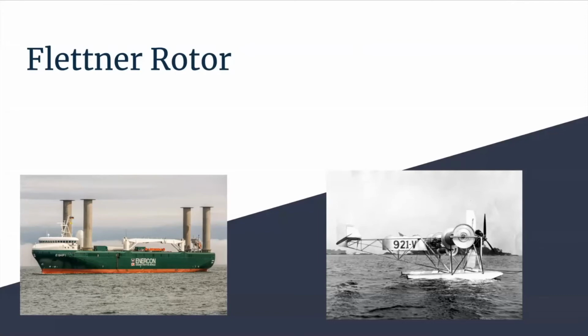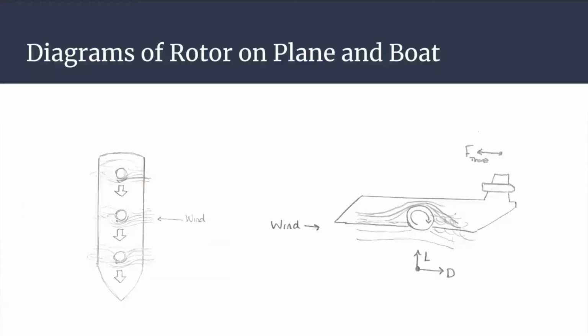This fluid mechanical dissection video will discuss the Flettner rotor. As seen in images below, Flettner rotor sails can be seen on ships, where they are a common occurrence in order to improve fuel efficiency, and on planes as a substitute for wings. The basic principle behind a Flettner rotor is that the rotating cylinders can utilize free-flowing velocity streams to provide a net pressure force perpendicular to the flow of the air around it.